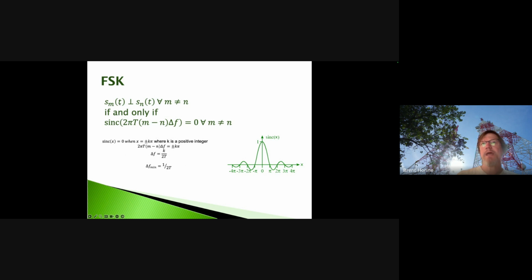So if we have a large set of different symbols that we're trying to send using this FSK modulation, then we want the frequency spacing of all those to satisfy this k over 2T. Now, if we're pretty far spaced in frequency, then we're going to satisfy that.